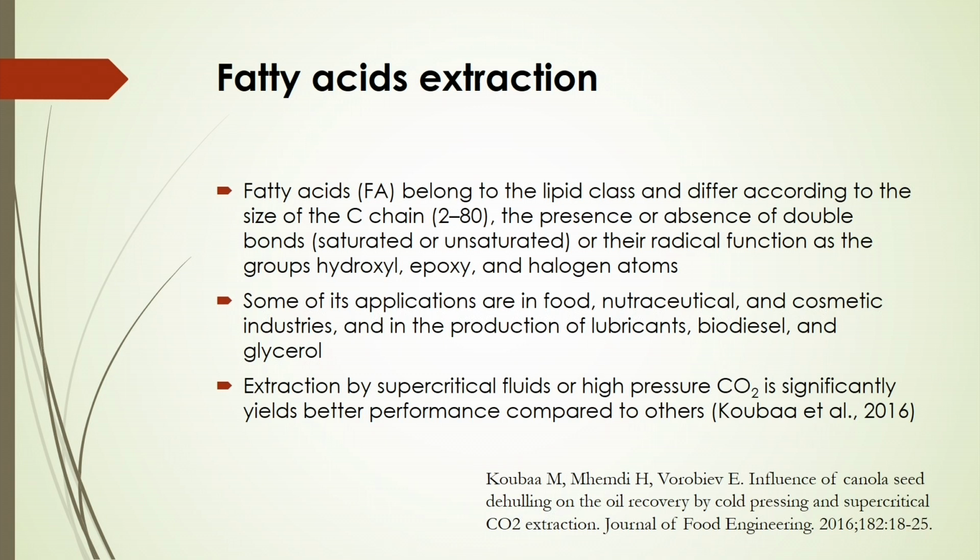2016 reported canola seed dehulling on the oil recovery by cold processing and supercritical carbon dioxide extraction, showing that this type of extraction is very useful even in fatty acid extraction. So, that is why process intensification by supercritical extraction is coming, based on green development or sustainable development, or green synthesis you can say.